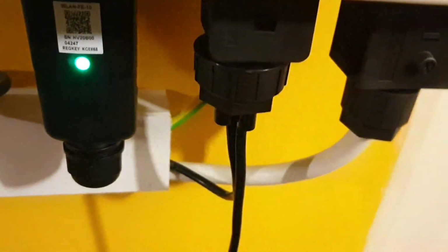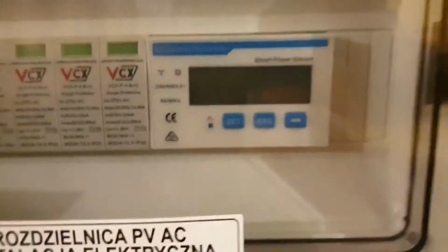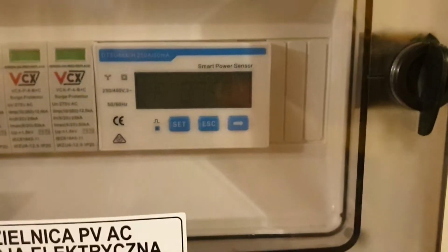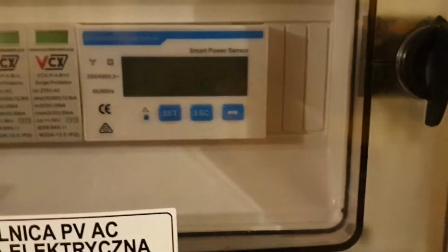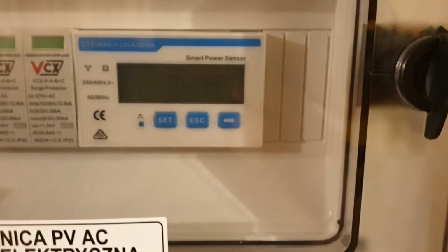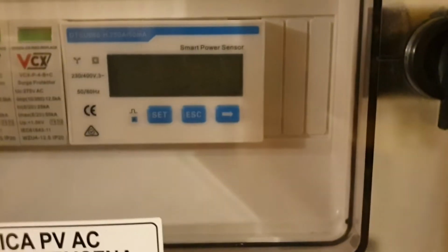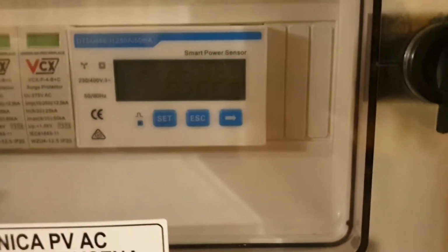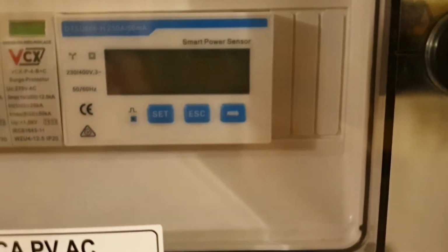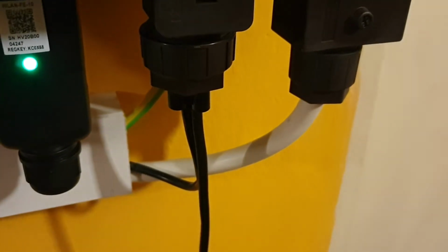And here I have two cables, because the first is used by the smart meter. It's the vendor solution to monitor the power and the voltages in my household. On one end it's tapped before the main fuses, and on the other end it's connected using that RS485 port to the inverter.